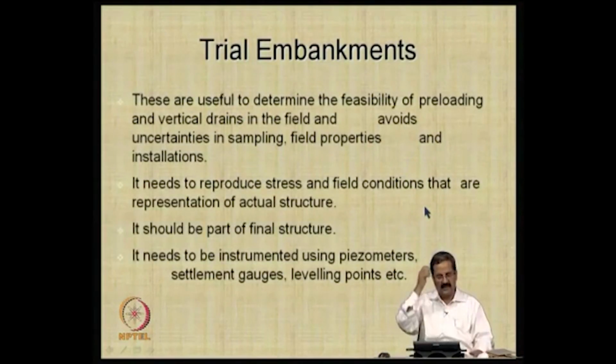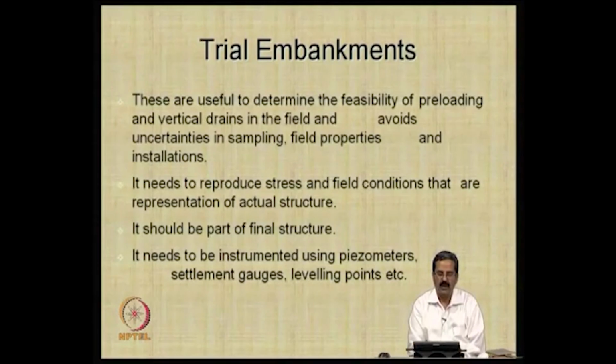A very important thing is that when you are trying to construct the preloading and all this equipment, or even the sand drains or the prefabricated vertical drains, one should really do some sort of trials in the field. How do you do the trials in the field? Actually, this is a very popular concept in the west, particularly in Netherlands, and if you go to Scandinavian countries like Denmark, Finland and all that, the soil is so soft, many of the techniques will not work. The maximum ground movement techniques were done in those areas in the 60s and 70s, and even now it is an exciting area for geotechnical engineering.